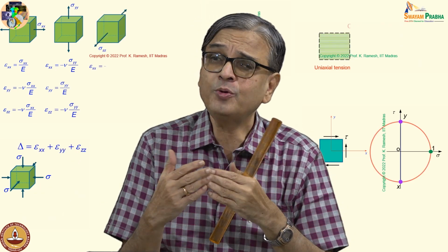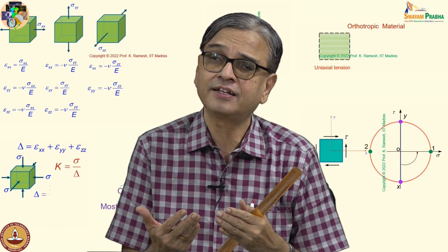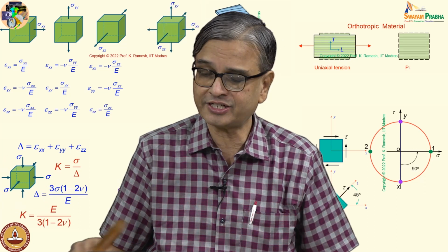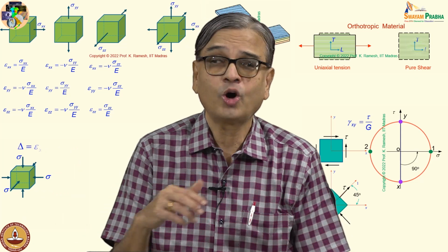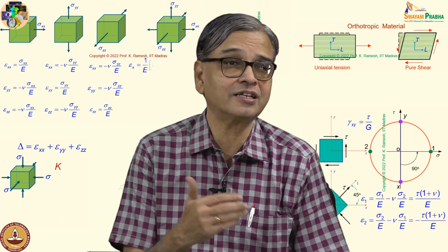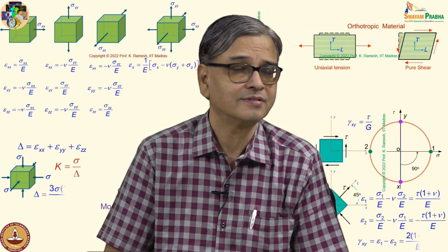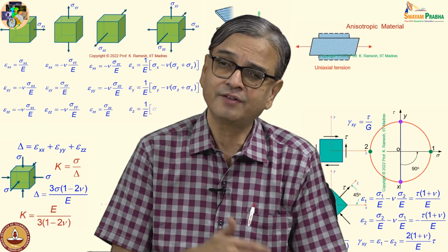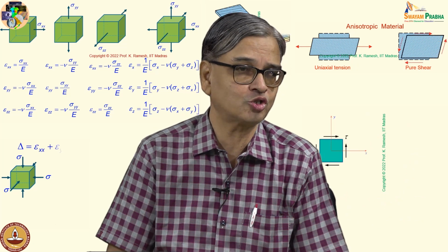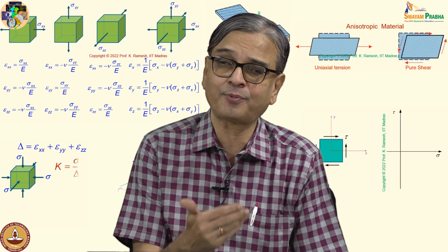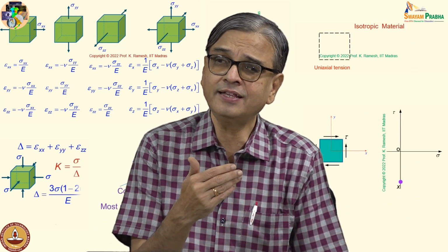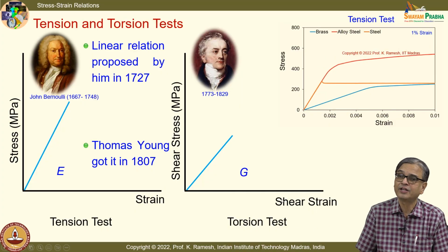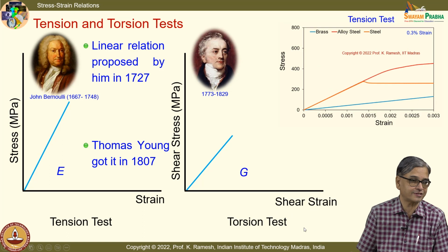When I come to measure the strain, we have also had a lecture on strain gauges. How many strain gauges do we use to measure the torque? We used 4 of them. We wanted to amplify the signal. Even in principle, one strain gauge also you can use, but it should be aligned properly. So even the measurement of shear strain is not going to be simple when I do the torsion test.